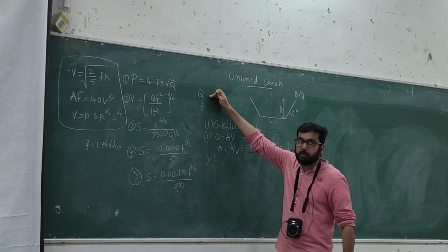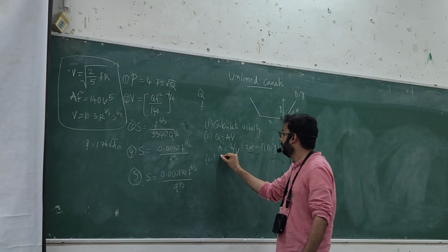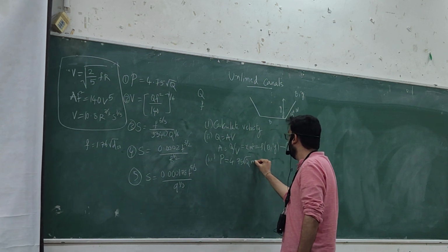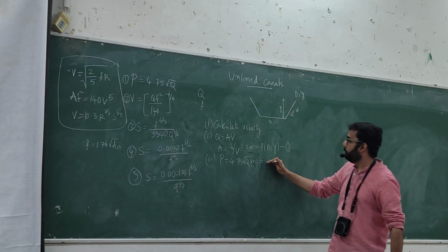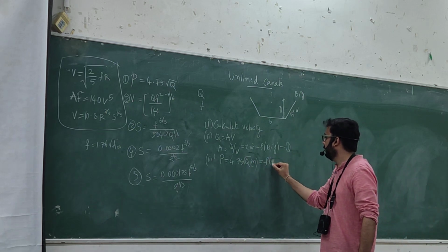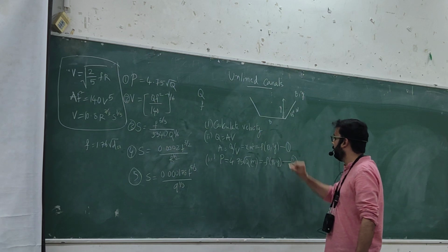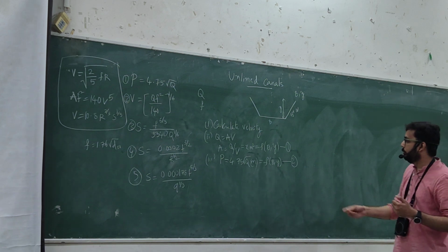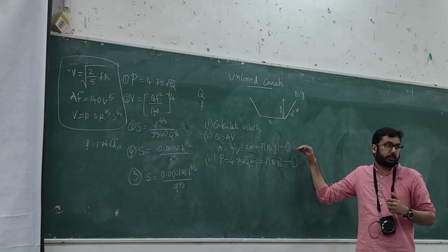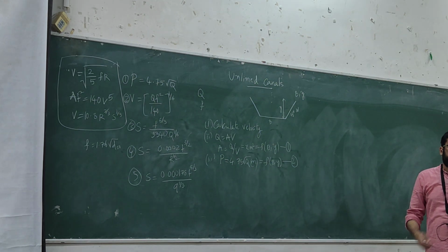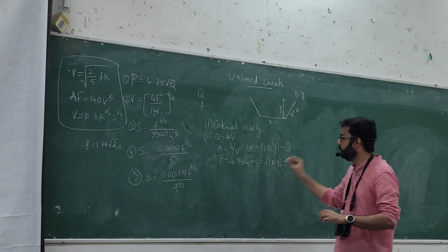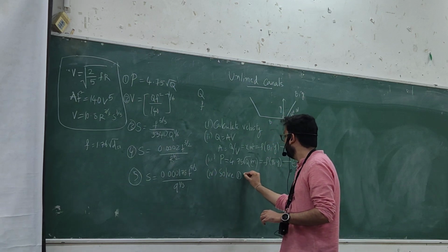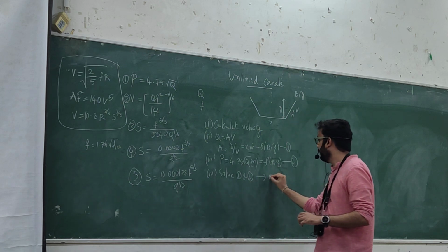Now based on discharge, what else can we calculate? Perimeter, P. And this is in units of meters. So this is also again a function of B and Y. So this becomes our second equation. So we have two unknowns and two equations. So if you solve equations 1 and 2, then you would get B and Y.